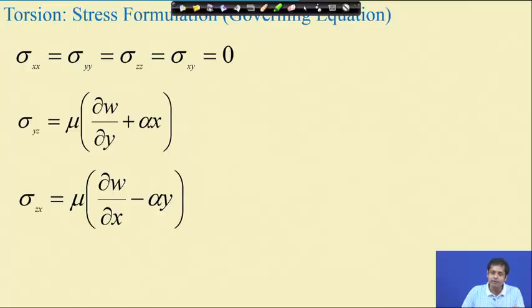When we write in terms of strains, it essentially gives you how the different strain components are related to each other, that we directly get from the compatibility of displacement. Now, if we replace strain by stresses, the expression that we have is the compatibility equation written in terms of stresses. If you recall, the Beltrami-Michel equation is essentially that, but let us not write that equation directly. Let us derive this compatibility equation from the information that we have on the screen.